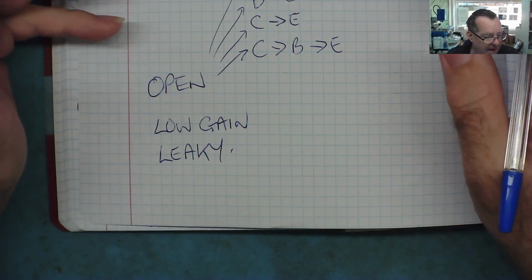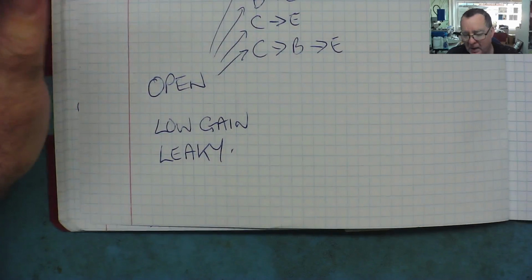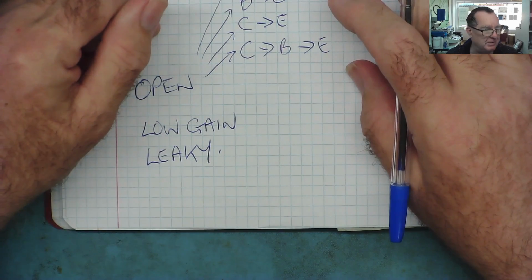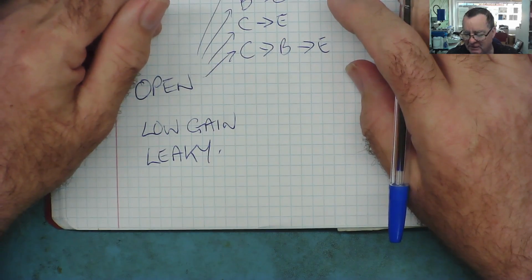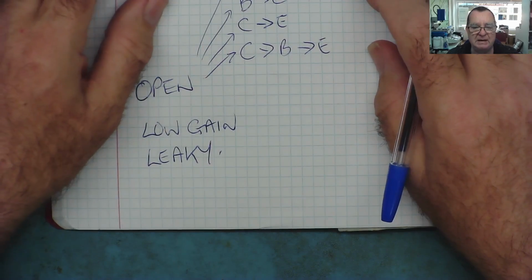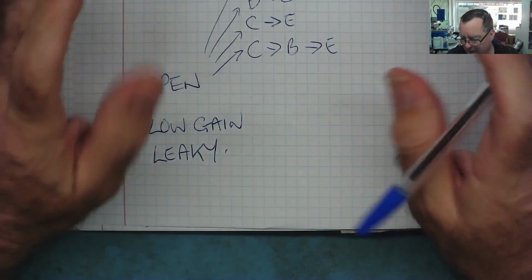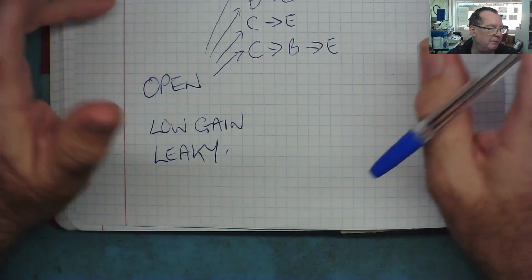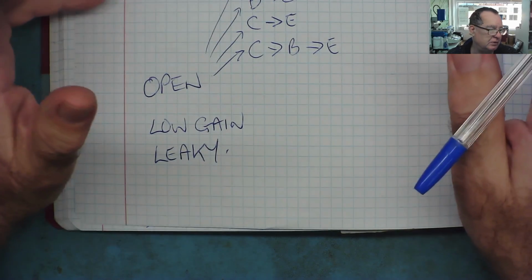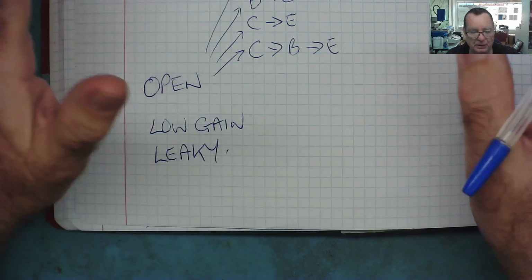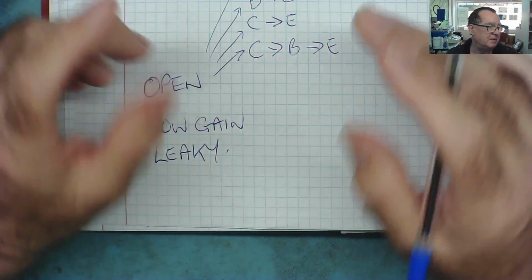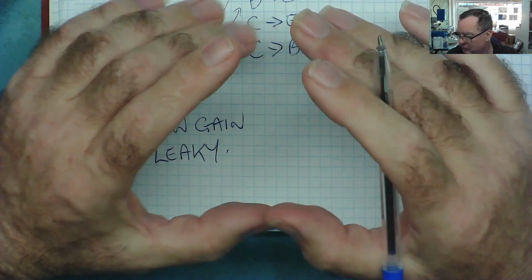Transistors can actually fail in quite a few esoteric ways. They can go noisy, they can become temperature sensitive, so the gain varies too much as temperature changes. They can do some pretty weird things, to be quite honest. And I think you'll find those more commonly in analog circuits such as amplifiers and radio frequency circuits. I'll be quite honest with you, that's something of a specialist subject on its own.